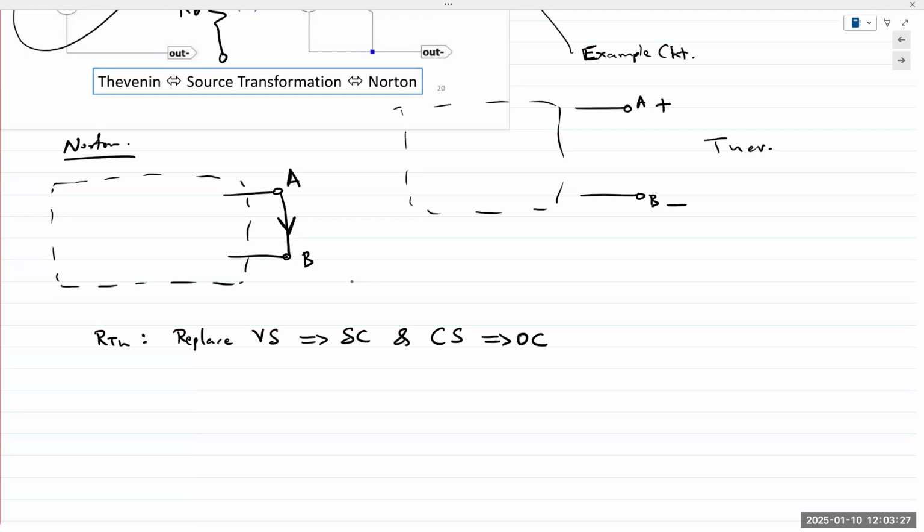The question being asked is, would I ask you to show the circuit diagram for RTH? And the answer is yes. I will ask you to do that. And sometimes you cannot manually find Req. Sometimes the circuit configuration is such that it's impossible. So then you simply use Ohm's law, because the relation between these three quantities is VTH is equal to IN times RTH.